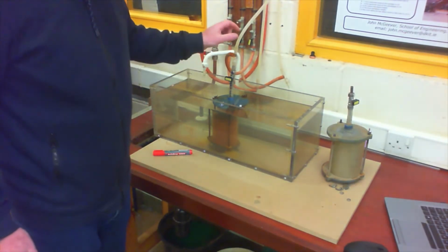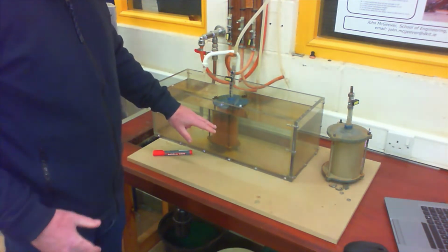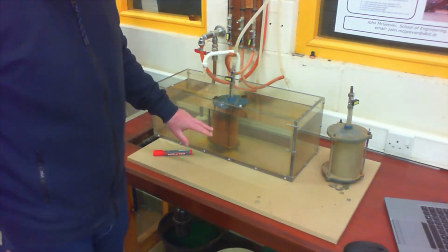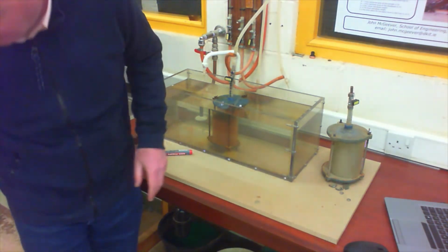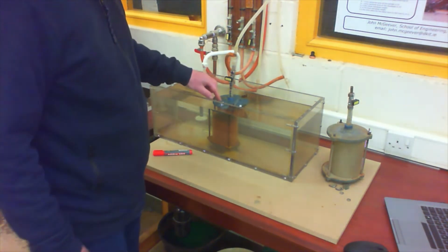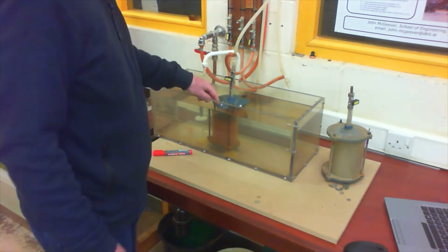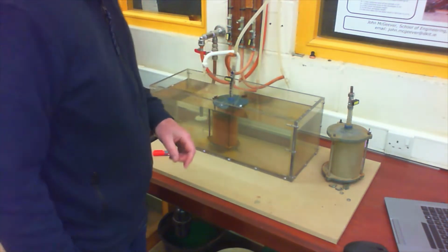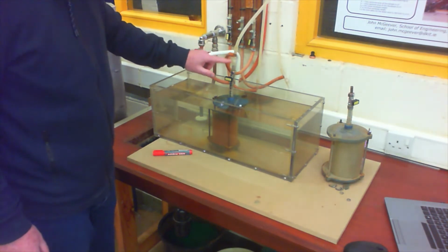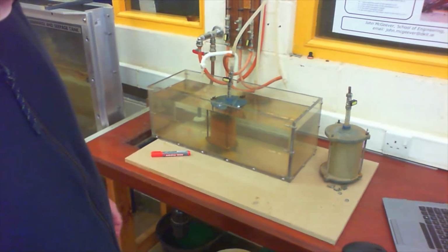So I've prepared a sample here that's a kind of silty type material. It's actually a fine ground shale. It's referred to as a clay, but it's not strictly speaking a clay. It's a fine ground shale, and it's inside the cell here in the water, underneath the water level in the reservoir, and the water that's going to drain into that, and that we're going to use to measure permeability, comes down through this tube here. I'm going to move the camera in a bit closer here because it's quite difficult to see what's happening.